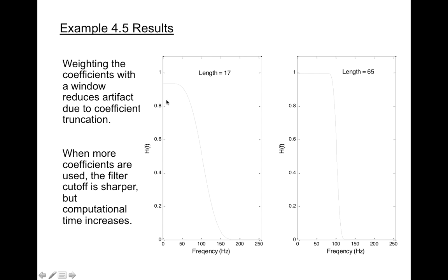And so what you see is for the Blackman-Harris, for this length of 17, I don't have the other one to compare with, but basically the cutoff oscillations are all gone. So you don't have the oscillations here either in the 17 or the 65. The 65 length window has a sharper cutoff as you might expect. The 17 length is a slower, more rounded cutoff. So our 65 element filter is approaching that rectangular window. We still have a finite slope, but it's better.